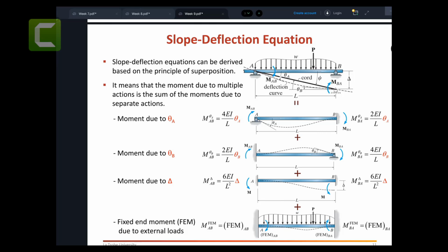So let's take one simple beam, a typical beam which has all the complexity, like all the loads and all kinds of settlements and everything, and we'd like to develop the slope deflection equations. Now, what is this beam? Let's start with the first figure. Let me explain that first figure. These figures that you are seeing are part of, let's say, a whole beam. Let's say someone has put rollers here, someone put this loading on it, someone put the P load and so on.